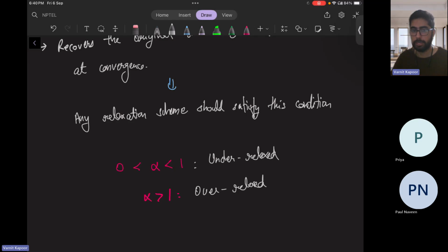No, that's not right, we'll get a diverged solution. We should maintain something like 1.2, 1.3. But it all depends on experience and expertise. And there is recent research about schedule relaxation, where a minimization problem is used to deal with that.